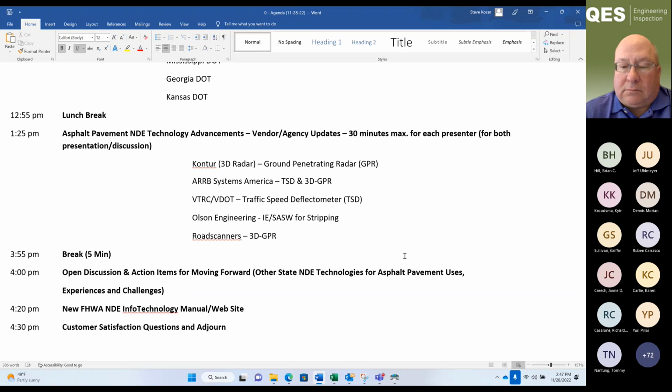Okay, is it just calibration of the sensor, or calibration of the whole equipment? The system. The system in terms of measuring the structural number or deflection. No, it would not be the structural number measurement, because that's a calculation. But it would be looking at the deflection values.